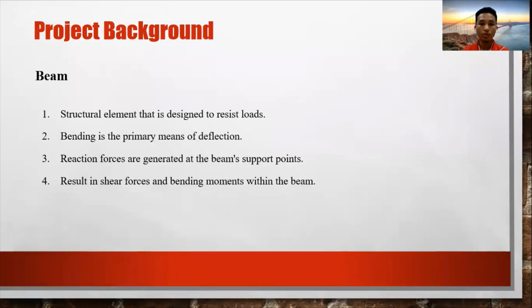Now I will continue by presenting the project background. A beam is a structural element that is designed to resist loads that are applied laterally to the axis of the beam. Bending is the primary means of deflection for it. Reaction forces are generated at the beam's support points by the loads applied to it. All of the forces operating on the beam result in shear force and bending moment within the beam, which causes internal stress, strains, and deflection.